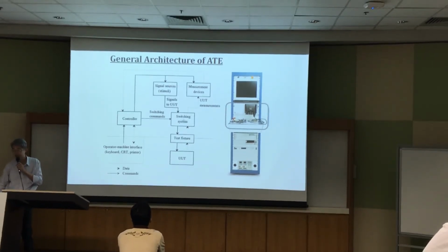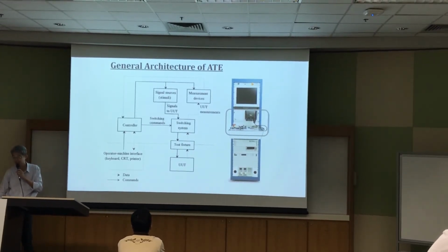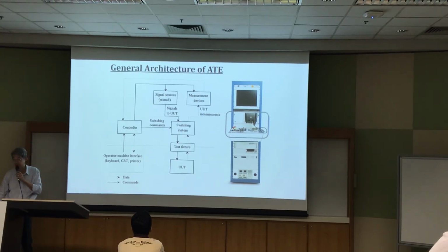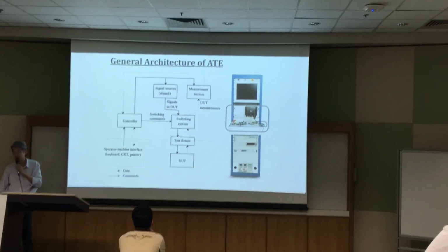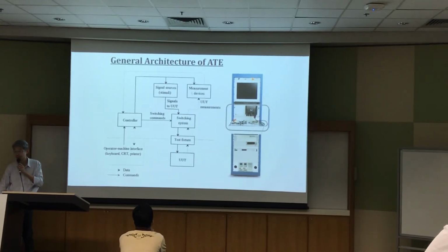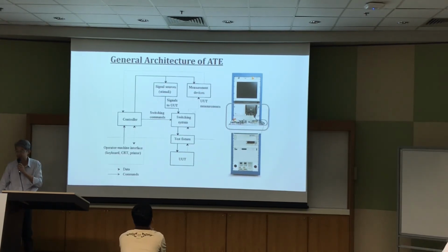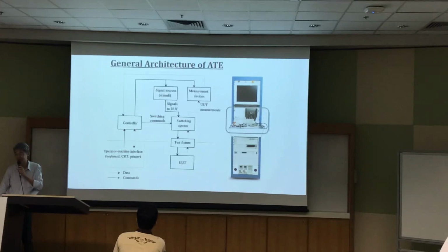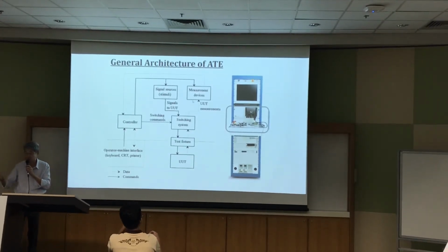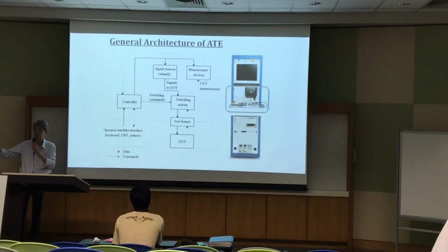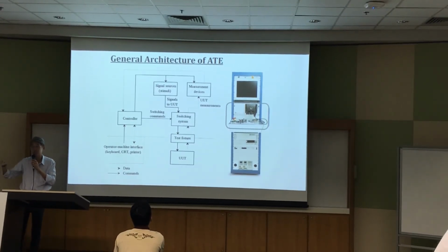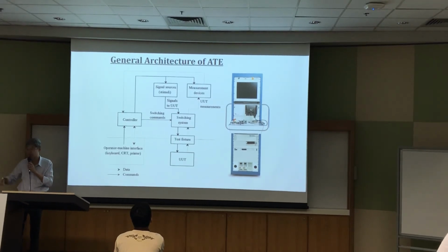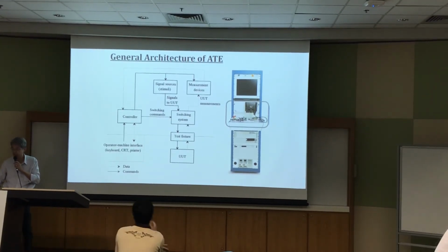Okay, so this switching system will switch all the signals to connect to the signal sources and pump into your so-called unit under test. Then the next moment it will switch over to the measurement instruments like the scopes, the multimeters, to measure the signal or the response from the unit under test, whether those signals are present or present but not ideal, to make sure the board is functioning. And this kind of test is normally the parametric format. They test the various components. And obviously the final test also uses some of this system.